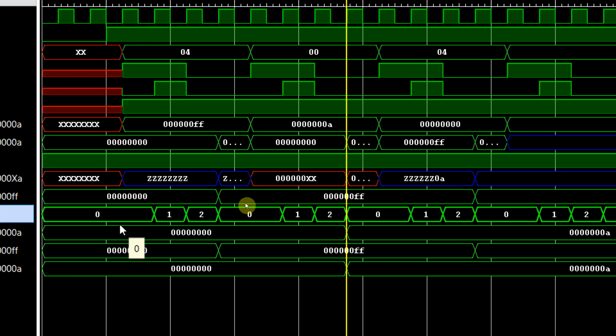So basically in your access phase, the registers we have seen in the GPIO controller code, whatever registers you want to update, those particular things will be updated according to the address which you have provided. If it is 0, you're going to access the data register, and if it is 4, you're going to access the direction register.